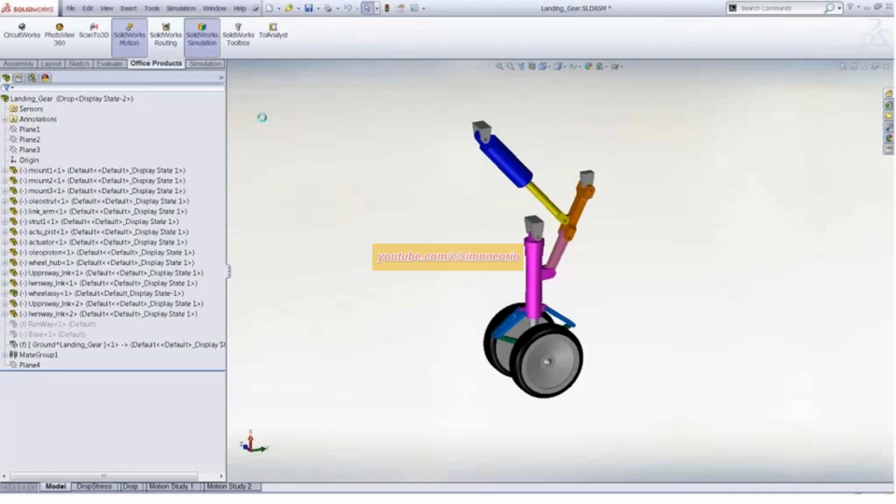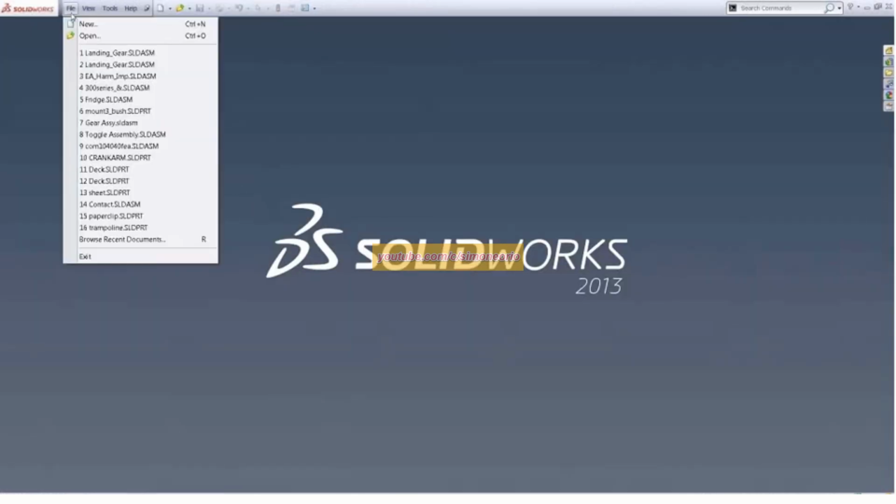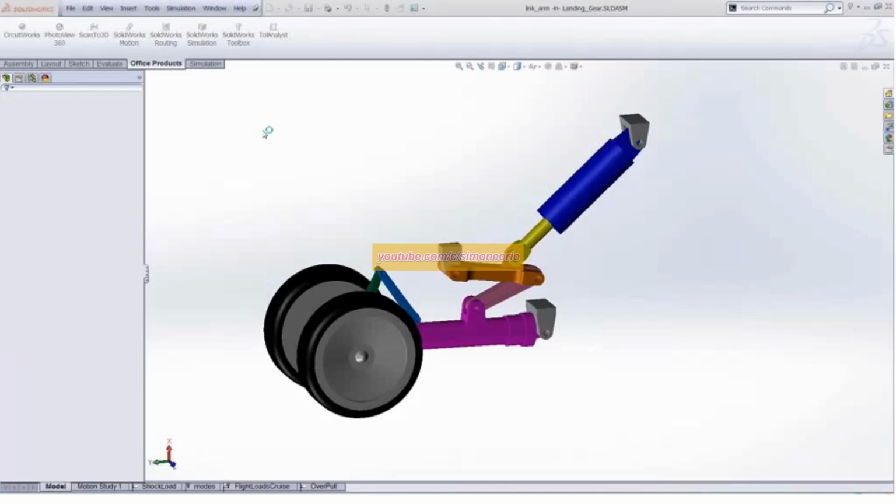The nice thing about SOLIDWORKS is that it's pretty simple to reconfigure our models. And since with our simulation tool, CAD is king, it's not like we've spent hundreds of hours building an FEA model, and now we're going to change our geometry and have to go back and modify the elements and nodes. Everything is driven off of CAD in SOLIDWORKS, so we don't need to really change much other than just shift the positions of our models using our mate constraints. And if we built a simulation when the model is down or up, we can just copy between configurations.